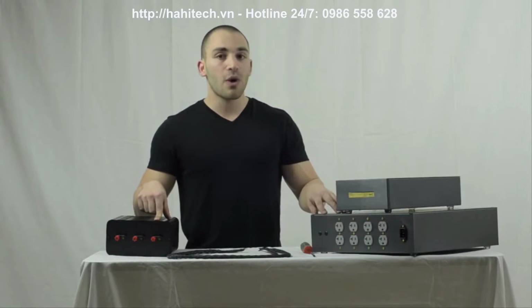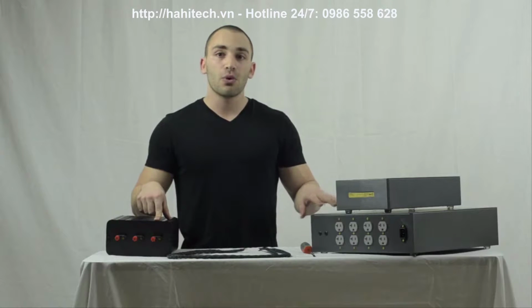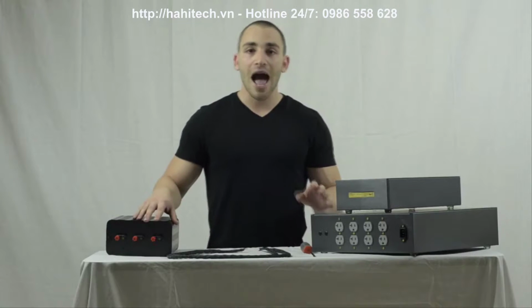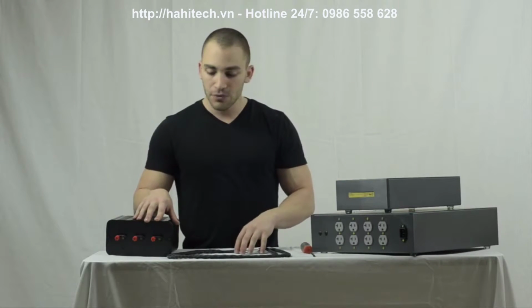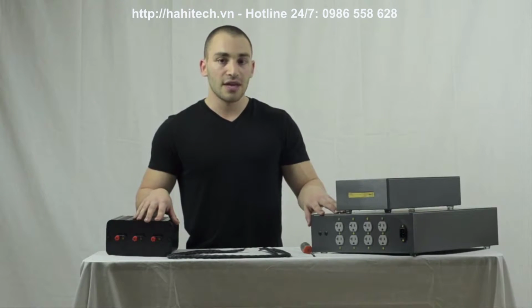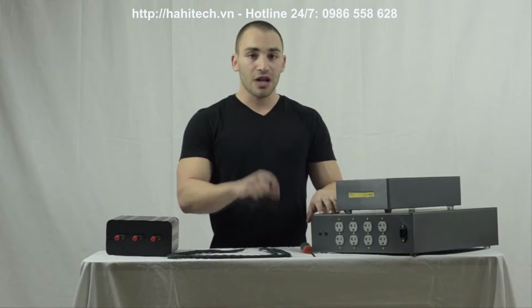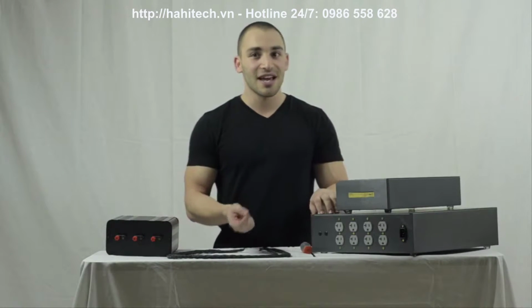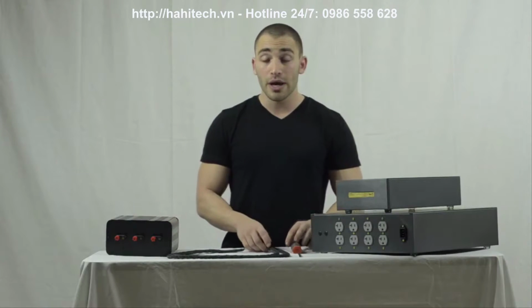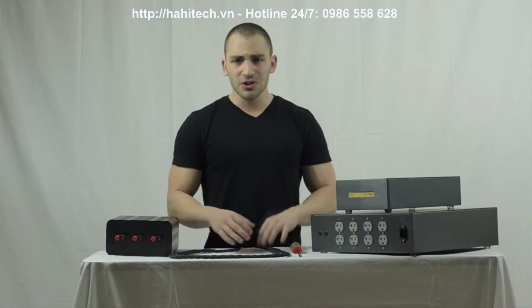And so that's part of why you end up actually introducing even more noise with a cheater plug, just because the ground is going to find another path to travel down to earth. The other issue with that is that when you have a fault current and the signal has to travel through an interconnect, for instance, you're going to have a lot of current traveling through a cable that's not designed for that kind of current or voltage, and it can cause a fire, it can cause all kinds of dangerous issues that you want to avoid, especially since it's really not going to fix your grounding issues.